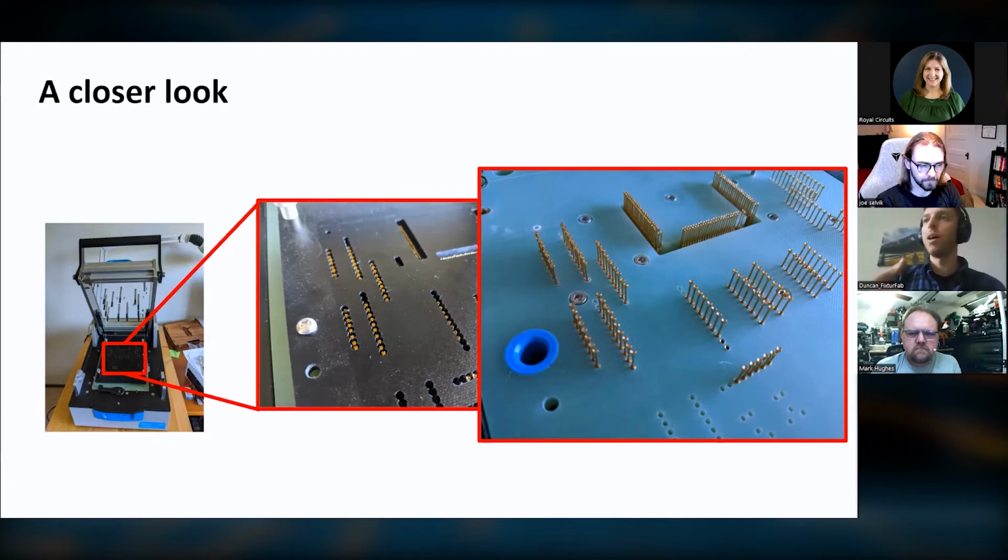On other fixtures, we'll use a physical micro switch or something like that. You can then use that to tell the programmable power supply to turn power on or off. You can also just use a relay, so you could have a USB controlled relay to turn power on and off. But you want to make sure you have a way of physically disconnecting power from whatever fixture you're designing.